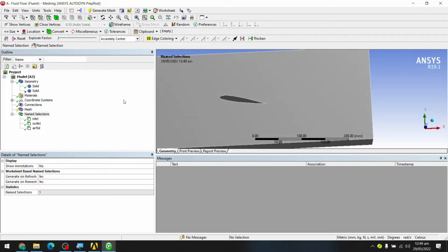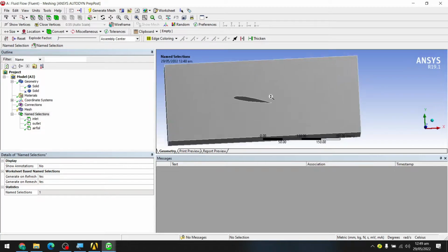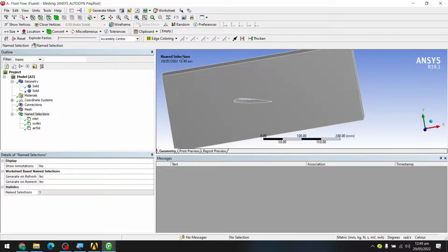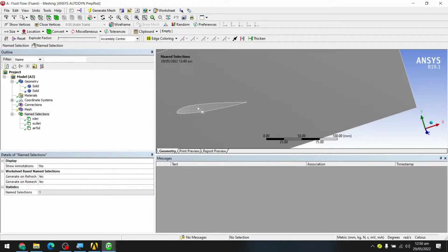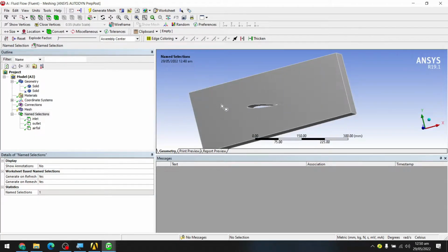Now we are going to create mesh. Now to create mesh, first we should think about which things are important for us. Is this region important for us for our mesh? No, this fluid will be stabilized. Now this region and our downstream region is important for us. So to save computational power, we will emphasize the mesh over here and make the mesh over here clean, and we can just mesh normally in the outflow regions.